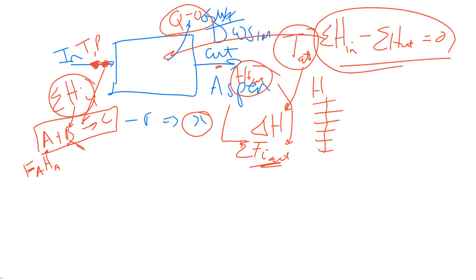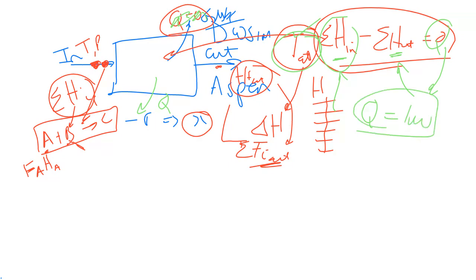If you say, I don't want it to be adiabatic, so there must be some heat flowing, Q, and you then specify the outlet temperature, what Aspen or DWSim will do is calculate the enthalpies at the specified inlet state and the specified outlet state, and therefore what your Q value is going to be, in kilowatts, from that reactor. That's the kind of energy balance you're going to do when you start modeling your designs in your design project, or even, I think, maybe this semester in Mike Heidenreich's subject.